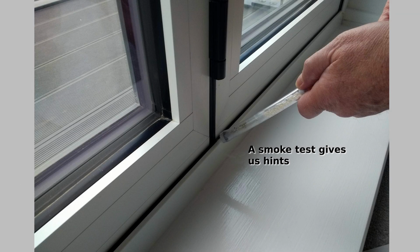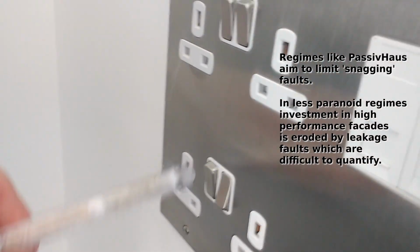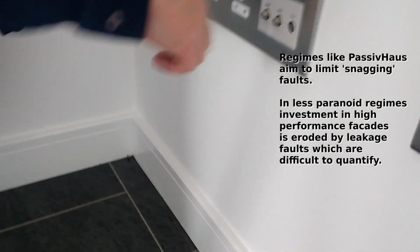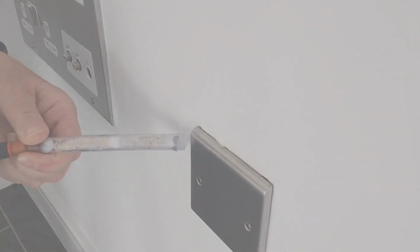Yes, if I do a smoke test during a blower door test, I get some hints about infiltration risks at a window. But many facade faults are hidden behind wall plugs and service openings. The thing is, they add up. I ran workshops for design teams seeking qualification in Passive House, showing participants the caustic impact of snagging and how to leverage blower door and smoke tests.